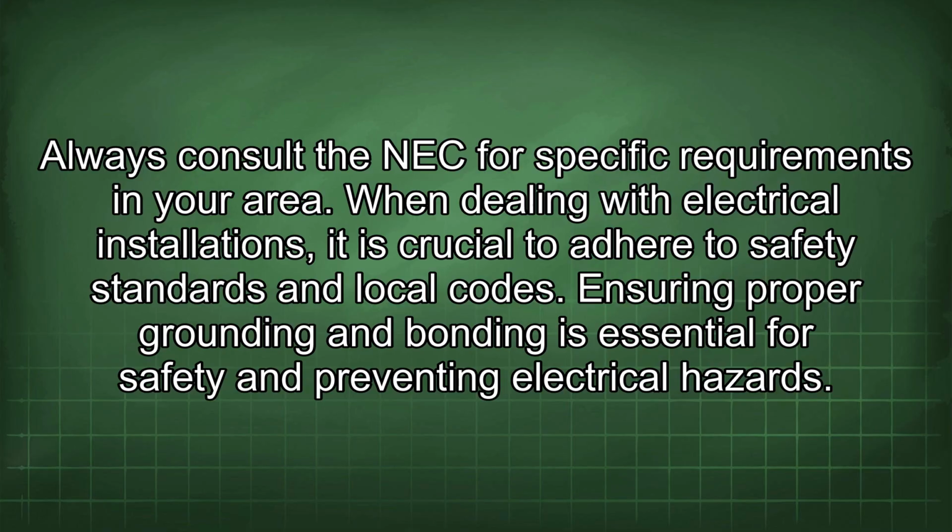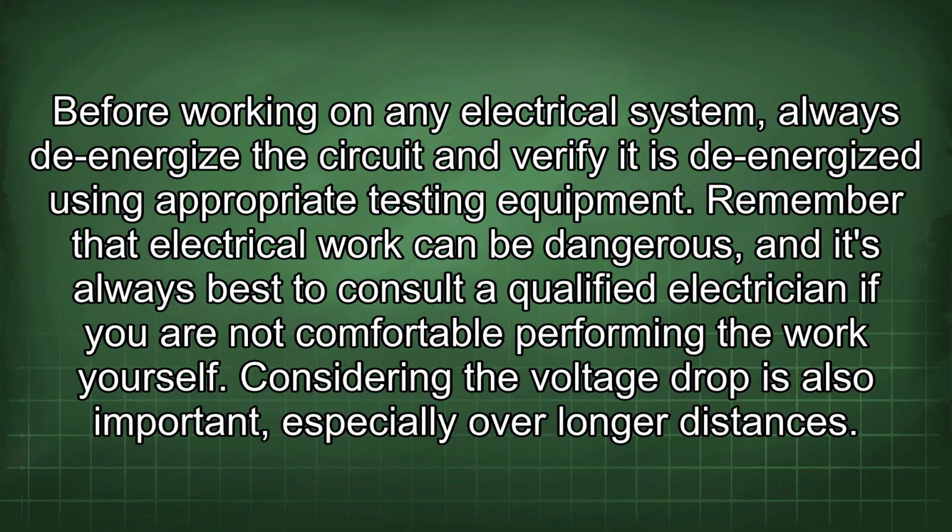When dealing with electrical installations, it is crucial to adhere to safety standards and local codes. Ensuring proper grounding and bonding is essential for safety and preventing electrical hazards. Before working on any electrical system, always de-energize the circuit and verify it is de-energized using appropriate testing equipment. Remember that electrical work can be dangerous, and it's always best to consult a qualified electrician if you are not comfortable performing the work yourself.